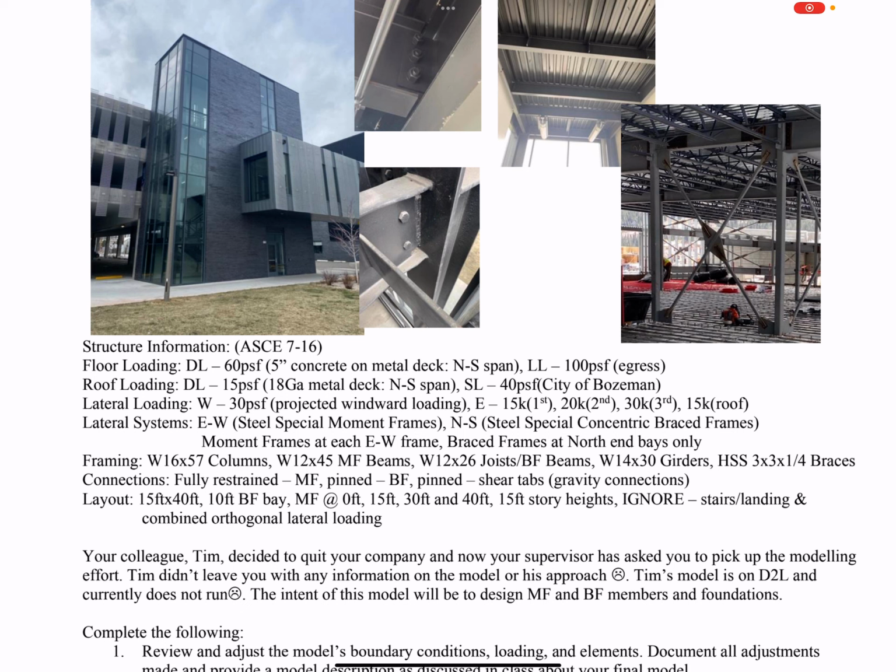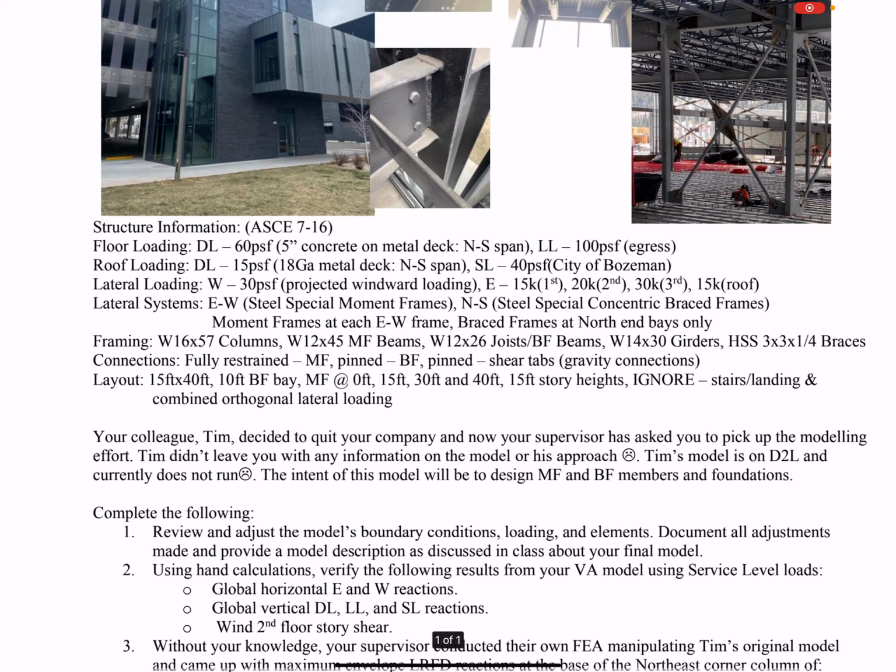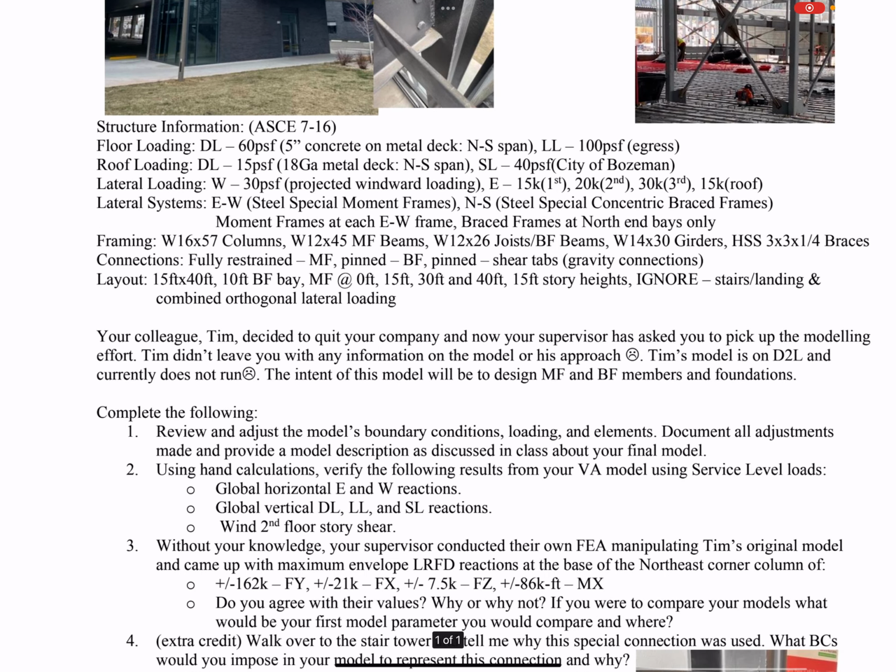36 ksi. No, what? No! 45. 48 or 50. No, it's moved up. It moved up. It's 50 now. Yeah. It's A500 grade C. It used to be A500 grade B. Okay? Which was 46, now it's 50. All right, that's the preferred specification, okay? So think about that, right? Those are some things I could change in this model pretty easily.